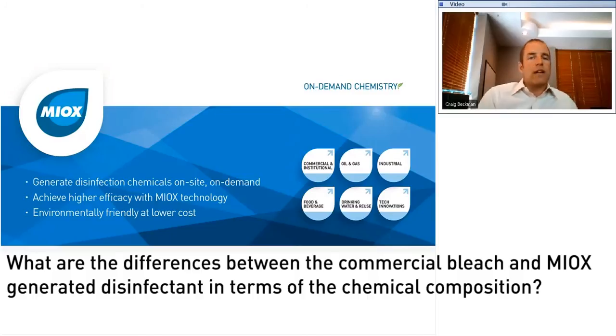In the warehouse that I was in, they must have had storage capability for 50 1-ton gas chlorine canisters. And they've now shifted a third of their production to on-site generation, where they simply store bulk salt. They have a tank of salt that makes a brine solution, which obviously is much safer than what they had. So that's how we would compare to gas chlorine.